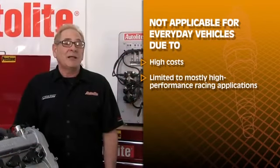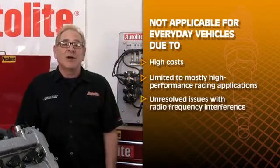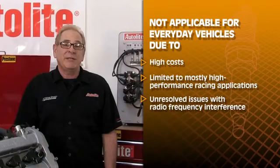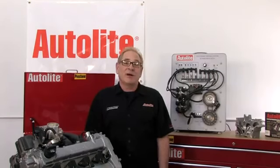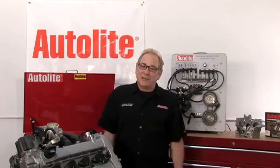Because it must use solid copper core wires and non-resistor spark plugs, it also has unsolved issues with radio frequency interference, which can wreak havoc on the PCM in a modern engine. Plasma ignitions have been around for 3 decades, so you can expect to hear more about them as these issues are resolved. So what can we expect to see next, technology-wise?